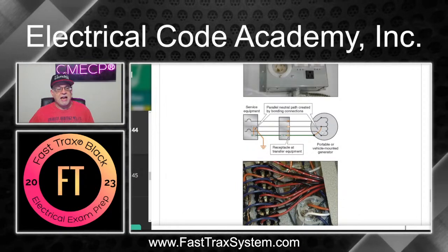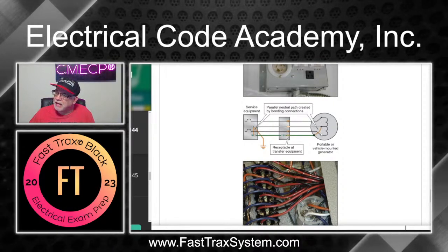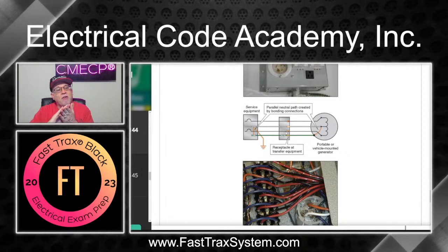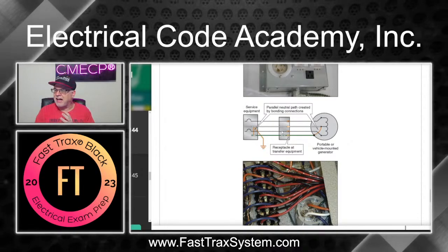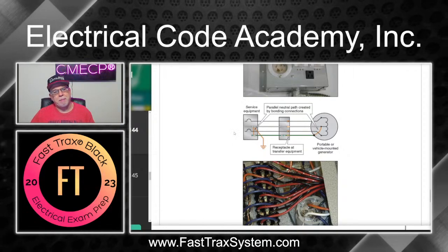So if you're using a portable generator or a vehicle-mounted generator that does have the bonding taking place in it, which is what you would use if it was a standalone, by the way, you're going to have to select a transfer equipment that does what? That actually switches and shuts off the neutral. Because if you don't do that, then it's going to create parallel paths for neutral current. And then, of course, all these bonded connections are now going to be energized with neutral current. So it's critical to not just buy components, put them in, buy a generator, and not know what your application is for.